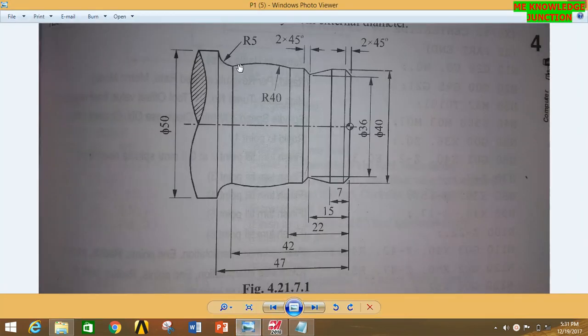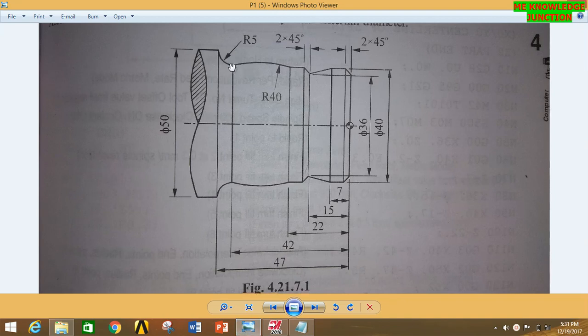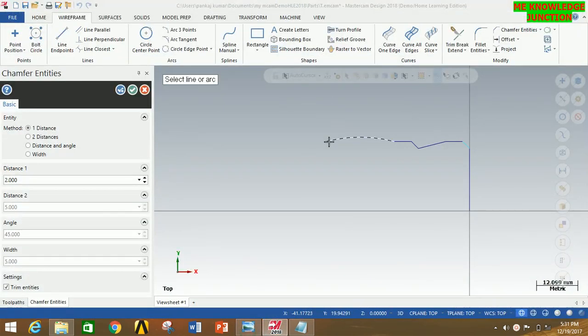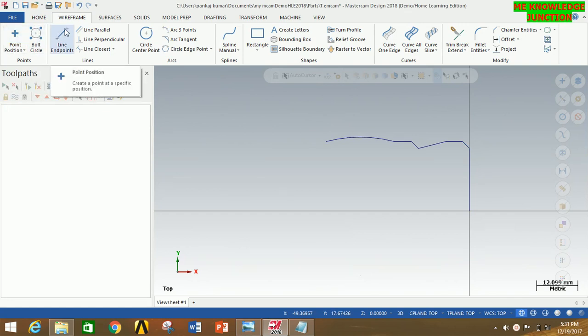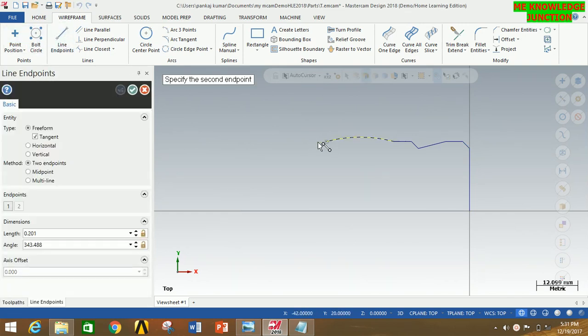Now we have to move from this point to this point. For that we are going to do from this point to this point and after this point to do it, and I will create the fillet. So we have to go 5 mm straight and then 5 mm upward direction. So now click OK and again click on line in point and click here and go straight and give the value 5 and then press enter and go again straight and give the value 5 and then press enter and now again go here and go straight in horizontal leftward and give here 10 and then press enter.